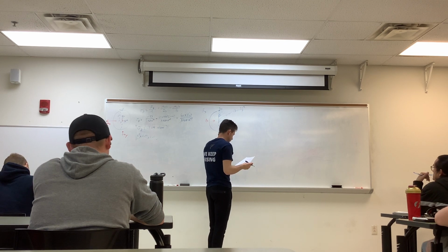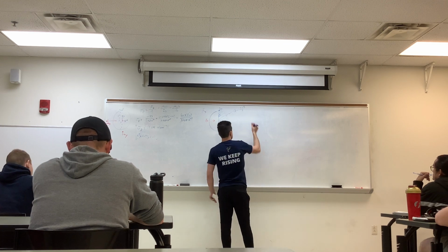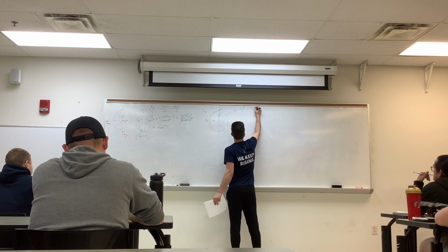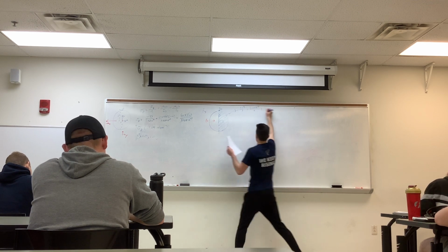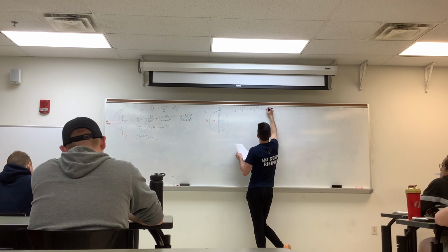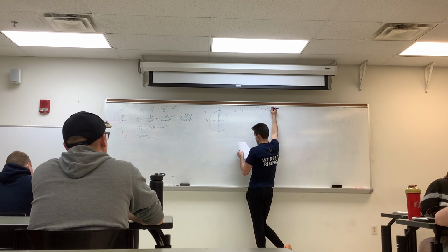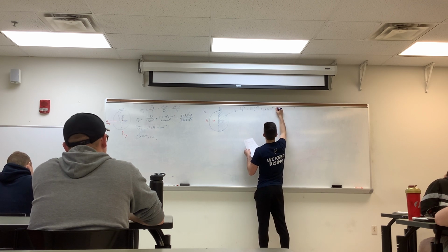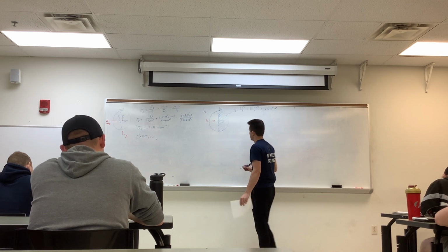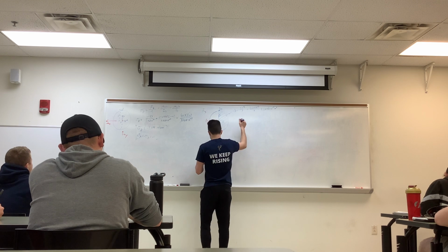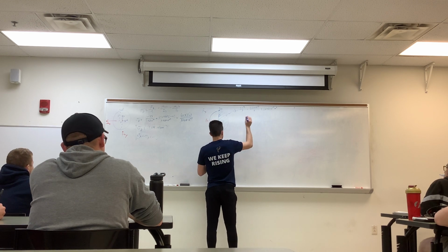And we get that to be equal to 2 times the radius, which is 0.025 cubed over 3. We get that to be 1.42 times 10 to the negative 5th meters cubed. So we have our shear flow, and then all we do from there is just plug and chug, really.